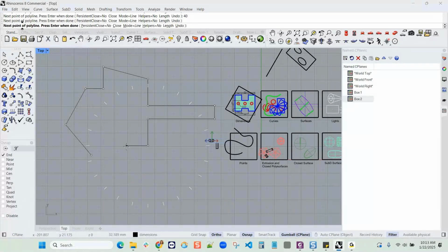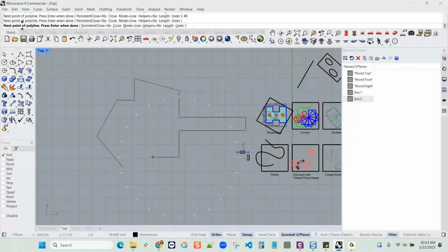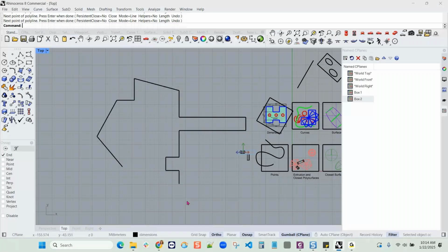That's called distance constraining. And distance constraining means that when you're in a command that's expecting a point, you can lock on to the angle with Ortho and just type in a distance, 20. But you do need that pick to actually accept that distance. It's still a little difficult because I don't get any feedback as to how far I'm going to draw that line segment.